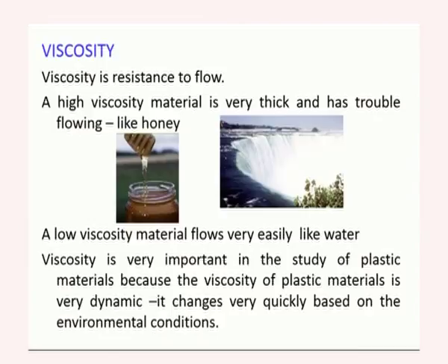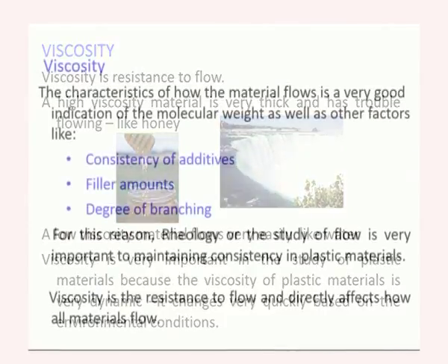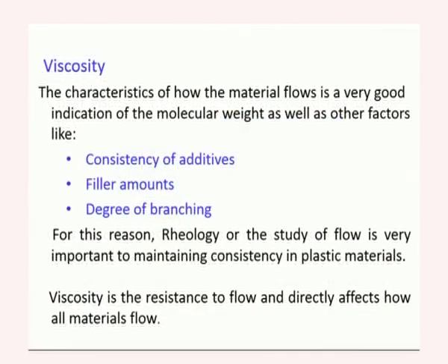In plastic materials, viscosity is more important, because when a polymeric material is melted, its flow behavior is more dynamic, and it also depends on many other factors. Therefore, viscosity is more relevant to plastics or polymers. The characteristic of how the material flows is in general a very good indication of the molecular weight as well as other factors. If the molecular weight is very high, then the material finds it difficult to flow easily, and if the molecular weight is very low, then it can flow very easily.